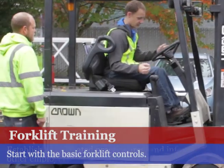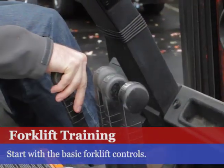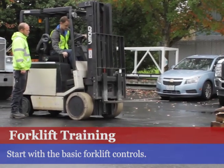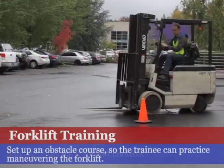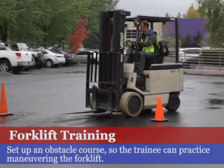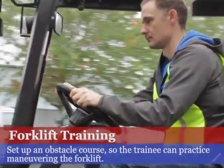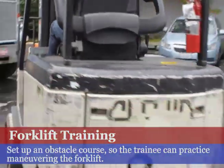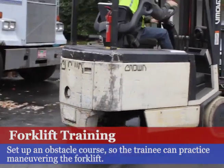Start with familiarizing the employee with the controls of the forklift. Have the trainee operate the tilt, lift, shift, and other controls, until they can use them confidently. Set up a basic obstacle course, so the trainee can practice maneuvering the forklift. The rear wheel steering will take some getting used to, so let them practice for a while. Be sure to point out the large tail swing that happens when a forklift turns.